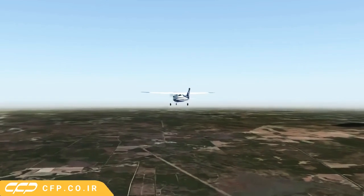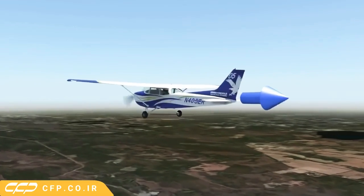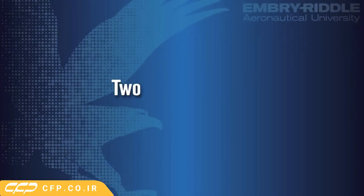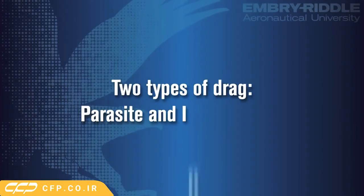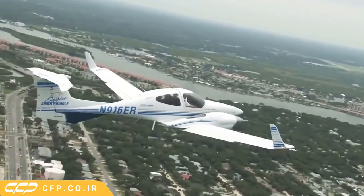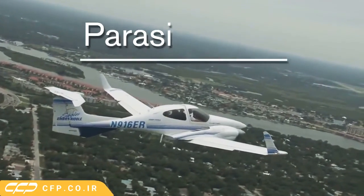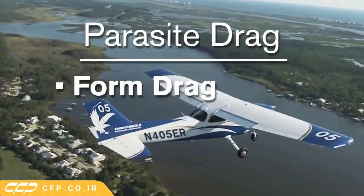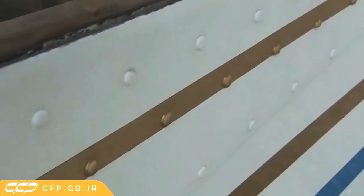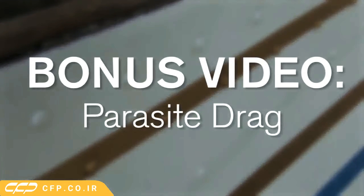And finally, we reach our last force, drag. Drag is the force opposing thrust, which limits the forward speed of an aircraft. There are two types of drag, parasite and induced drag. Parasite drag is a direct result of the air resistance as the airplane flies through the air. There are three types of parasite drag: form drag, interference drag, and skin friction drag. To learn about these three types, check out the bonus video on parasite drag.